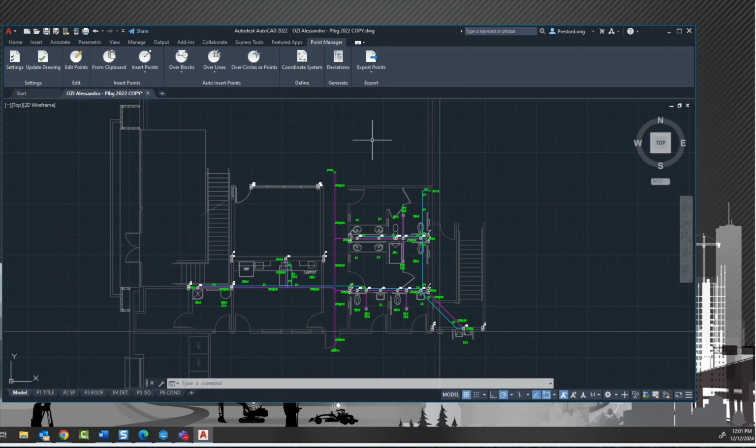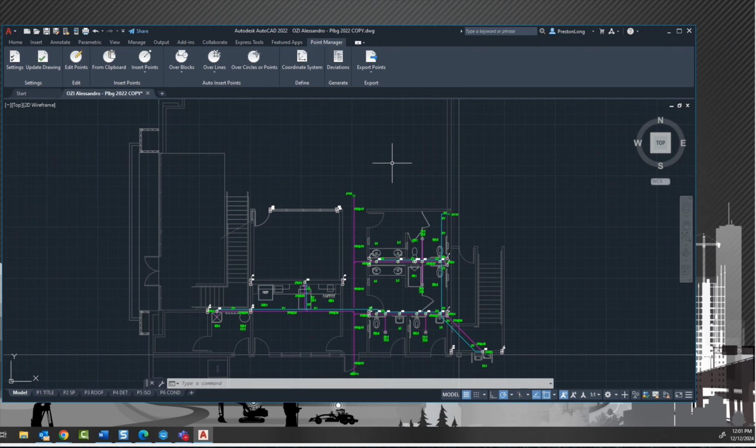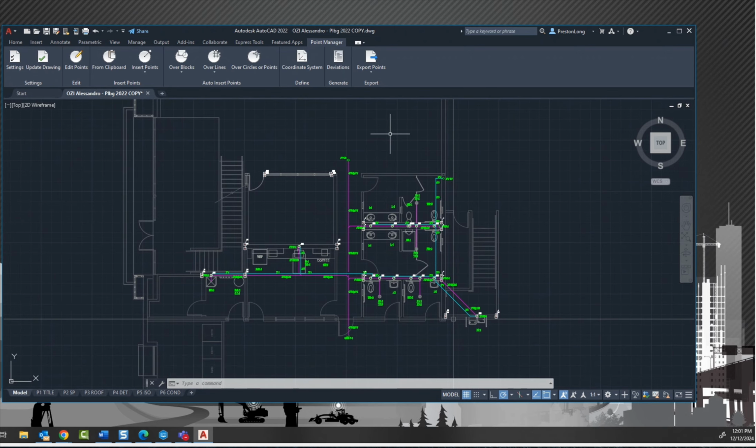If I measure off of something different, the electrical guy measures off of something different, the wall guy measures off of something different, we all wind up in a different spot. And then we're trying to prove who's in the right spot and who's not. So we try to make sure that we're on the same control, or pulling off the same lines as everybody else, and then you can just match it in your file, and you guys are ready to go.